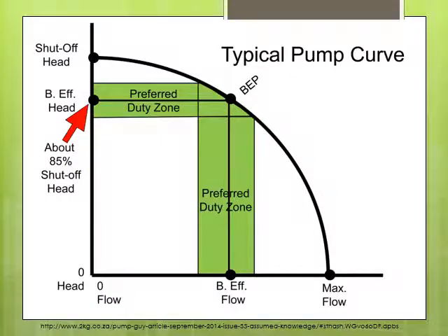Which brings me to this next graph, which talks about pumps being in their most efficient range. We want to make sure our pump is not overworking or underworking. For example, if we went for the biggest possible pump, it might spin up, pressurize the line, and then shut off until the line depressurizes and then cycle again.